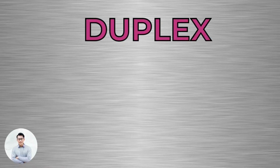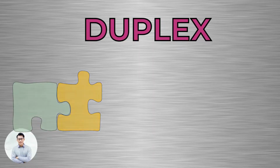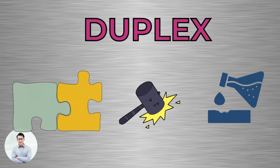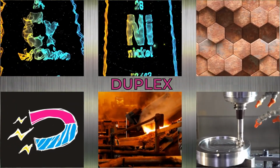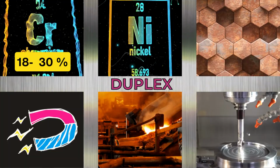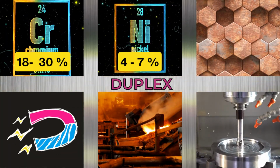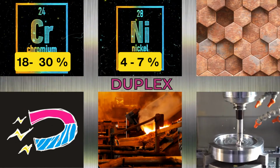Duplex stainless steel alloys have a two-phase, austenitic ferritic structure. They benefit from the advantages of both austenitic and ferritic properties, leading to increased strength, higher toughness, and broader corrosion resistance. Chromium content can reach 30%, much higher than austenitic alloys. The nickel content is between 4 and 7%.